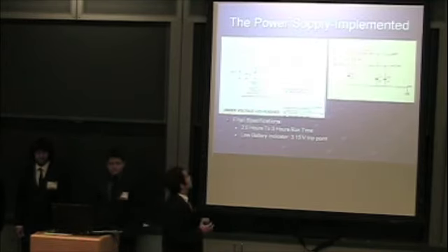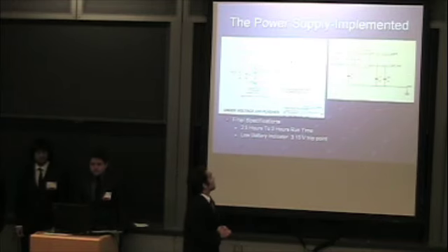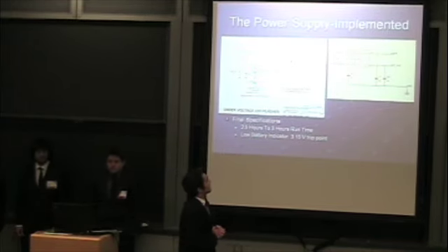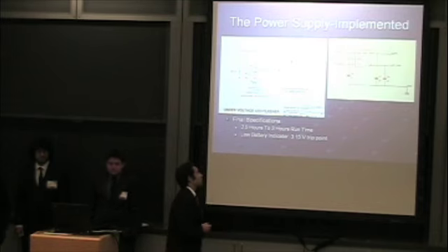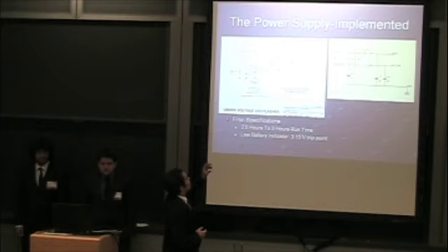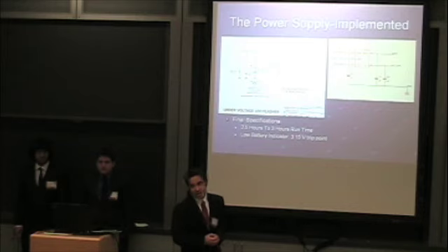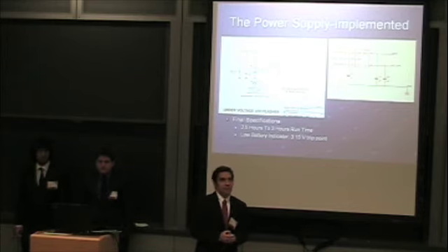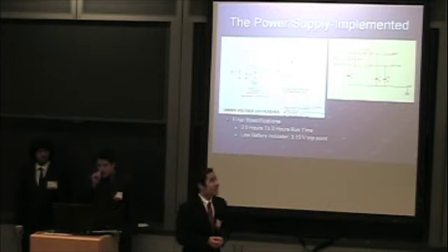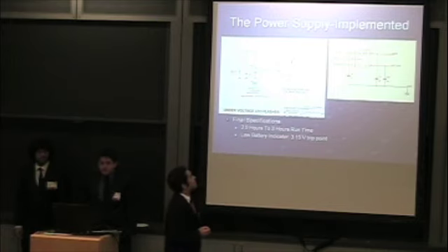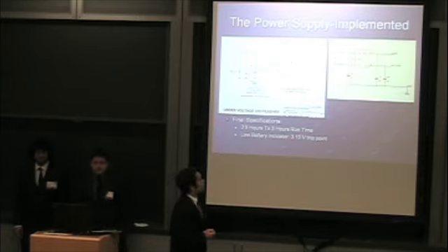Now, on the left, you see the template schematic used to design the low battery indicator, found from discoverservice.com. The focal point of this schematic is an IC from Panasonic, the voltage detector IC, MN1380 series. The schematic in this image here is for a trip point at 2.4 volts.